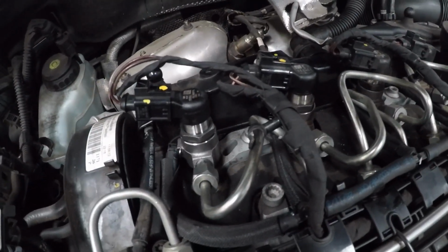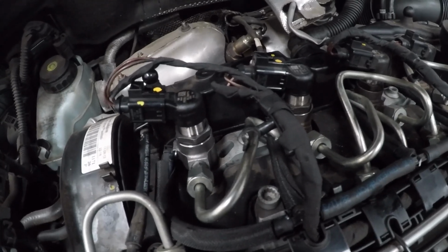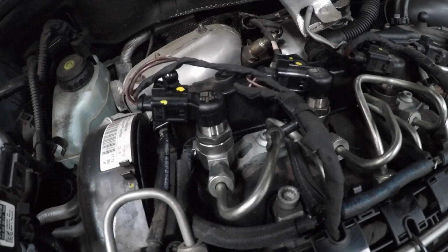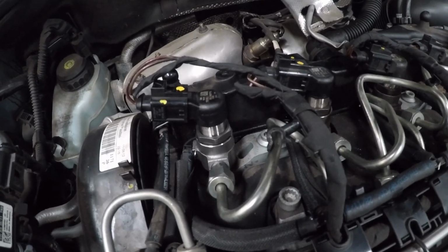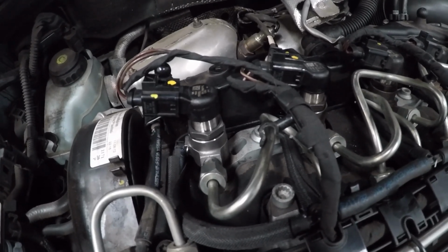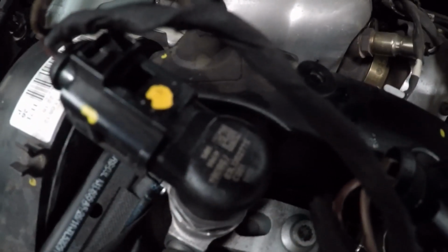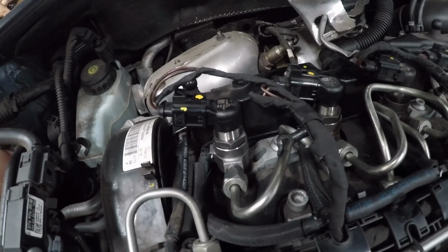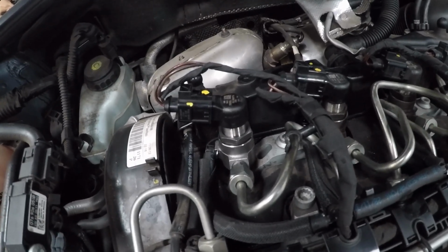Alrighty, the brand new injector is in. We actually did have to undo the second injector as well and lift it all up as one piece, just because of the way the bracket holds them down. But anyway, the injector's in. We're going to get that code from the top here, and I'm just going to take a photo of that one, take a photo of the original one, and we'll go over to the VCDS and we will code this in.